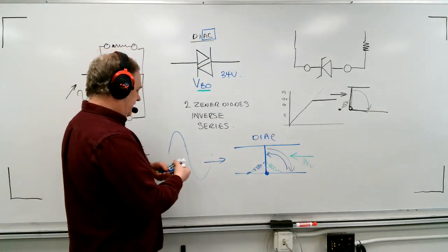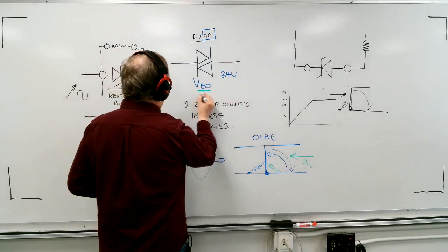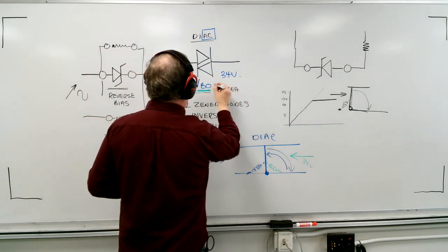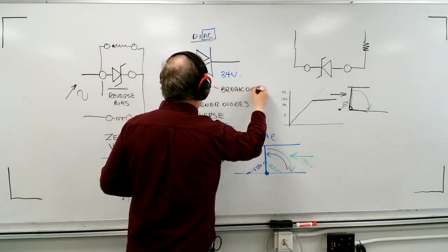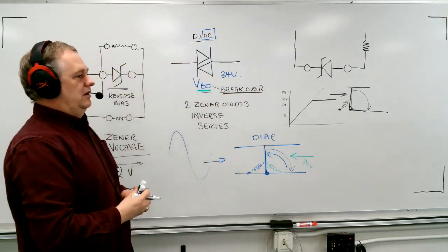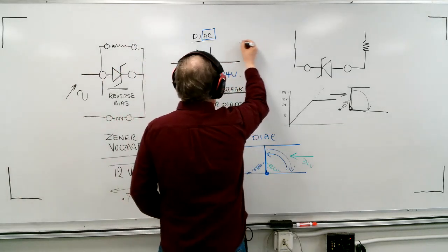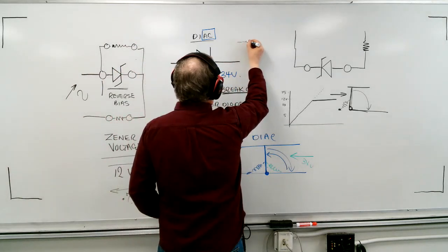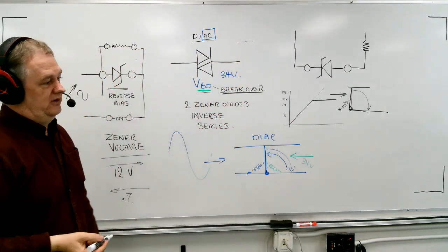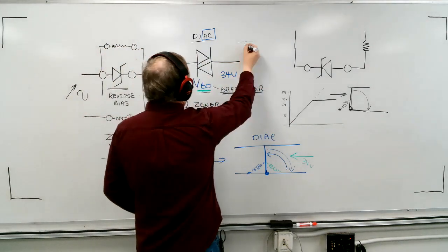Now, the interesting thing about this is that this value, this voltage breakover, okay, this is breakover, the voltage breakover is designed into the diac. So diacs, they can be very, very small components, sometimes about that big. So the one that I use in the lab, you can barely see it. So imagine this, and it's a 34 volt.